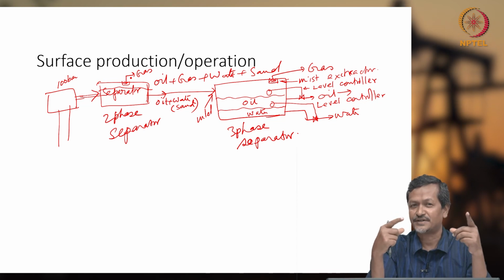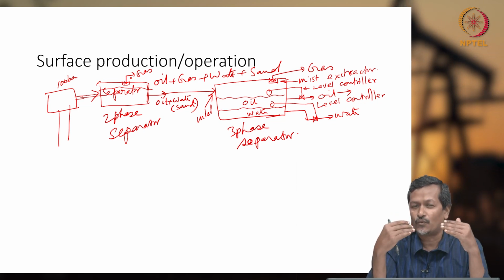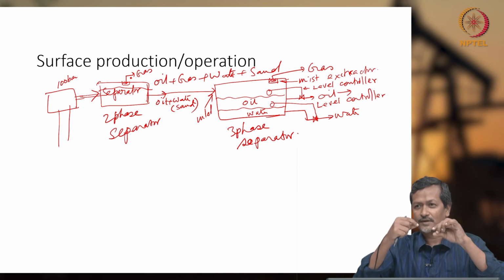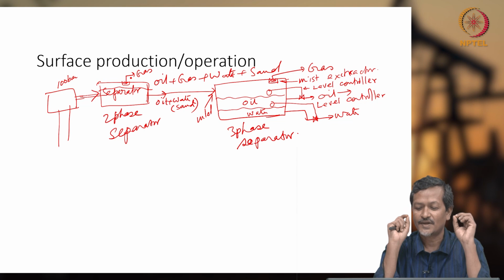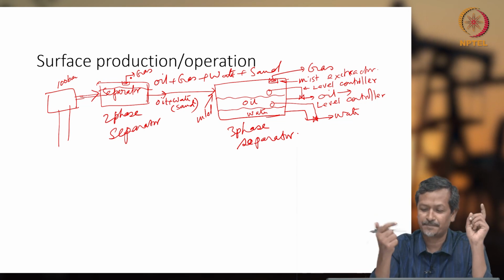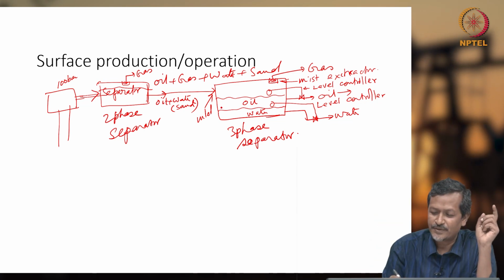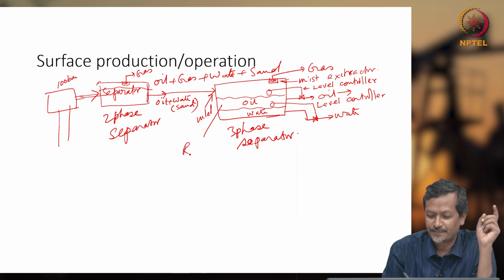If you are not giving sufficient time, then the water will contain oil particles or the oil will contain water particles. And how much time you have to give? That is called retention time. How much time it will be there here? It is called retention time.